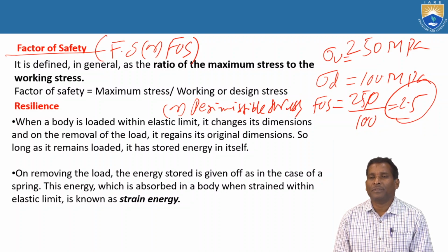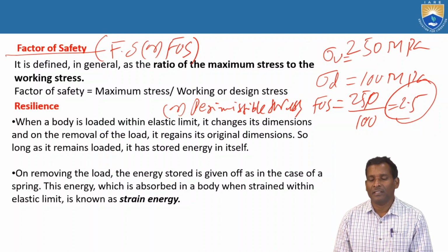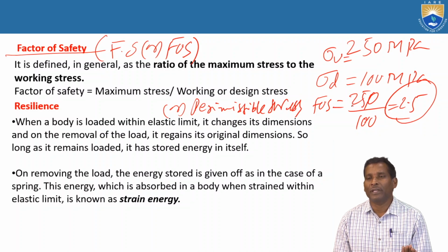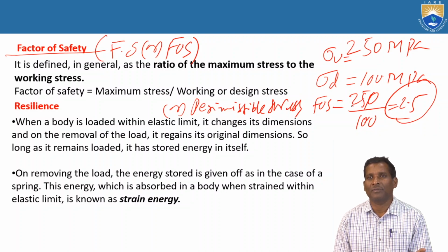By using this factor of safety, you may calculate other design parameters of a component. It means the component or product withstands this maximum stress or maximum load only, but your applied load is 100. Beyond the maximum load, if you gradually increase the load or stress, what will happen? The component will fail. So that is not safe.